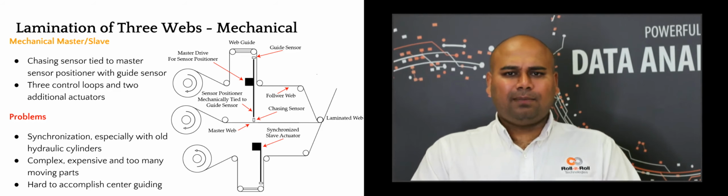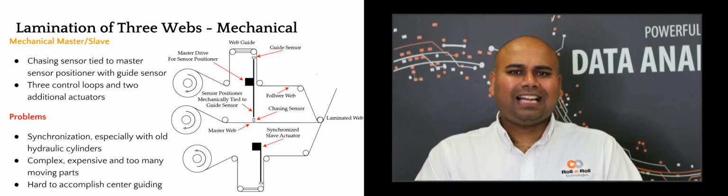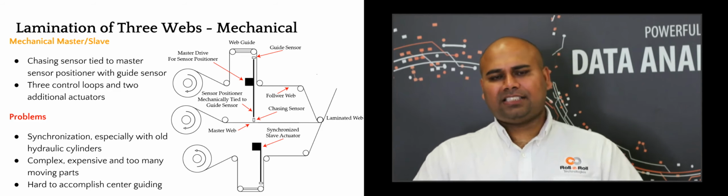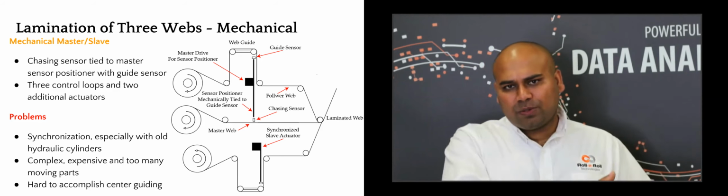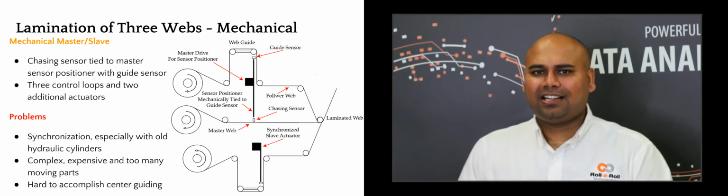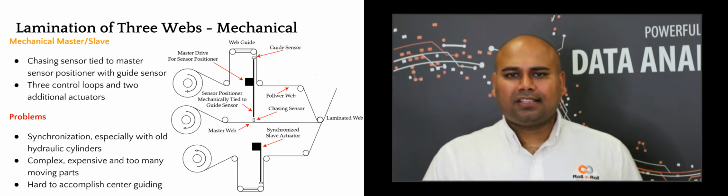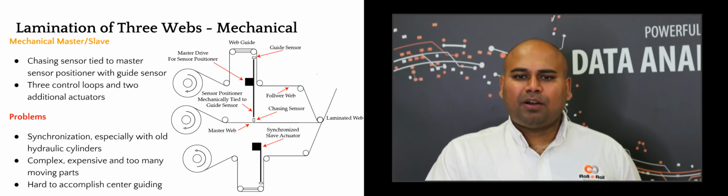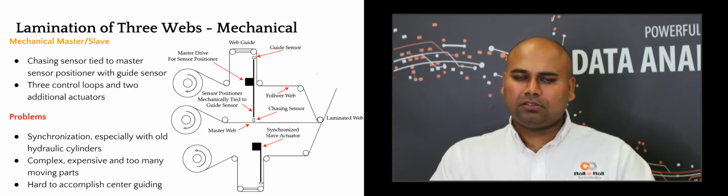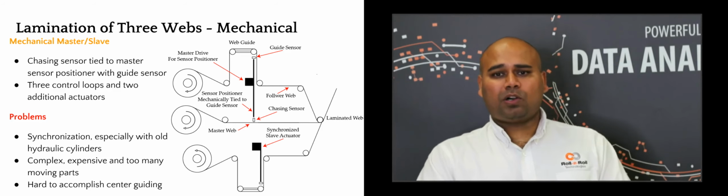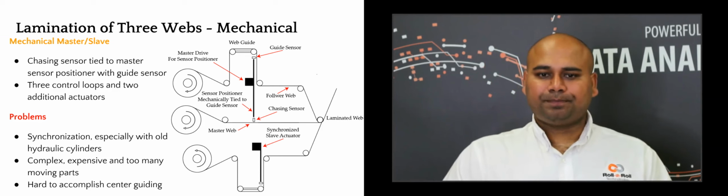Again, it's pretty complicated, especially mechanically. And then the synchronization is a common problem. Synchronization meaning that one actuator has to be exactly synchronized with the other actuator. Otherwise, this causes issues with performance, and any lag or slow response in one is going to provide an overall worse response for your system.